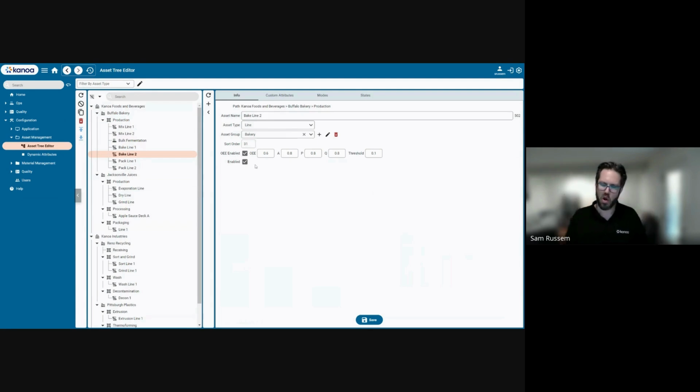When we do that, we're going to drop a UDT into the Ignition Designer for you to populate with the required data. Speaking of which, there's really only 3 tags that we need to run everything that you've seen here. We need an in-feed count, we need an out-feed count, and a state. It can get more complicated than that. It can get simpler than that too if you don't care about a quality calculation. But it can really just be as simple as those 3 tags, and there's a lot of power that you get with configuring your system properly here in the application with minimal data from the equipment.